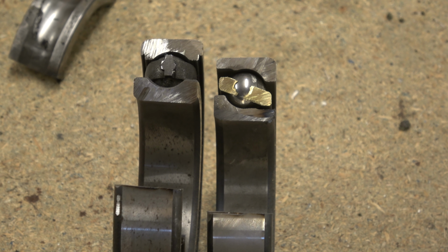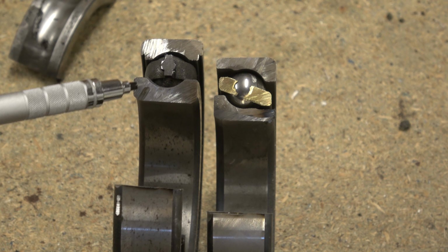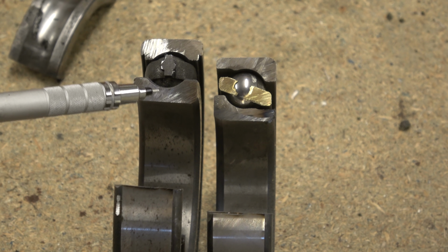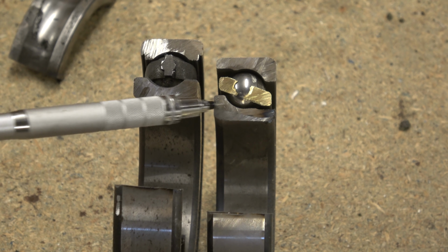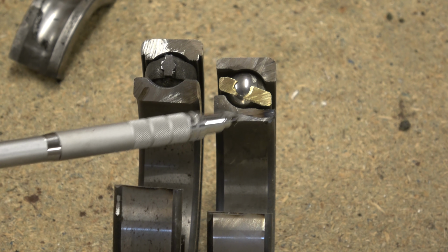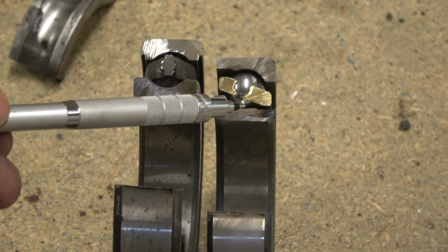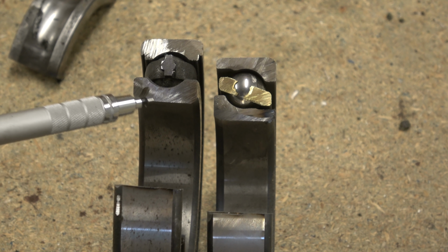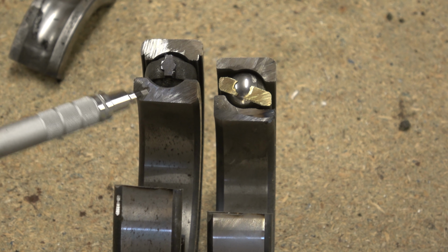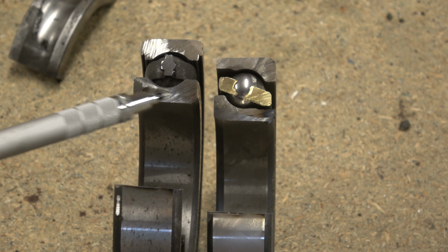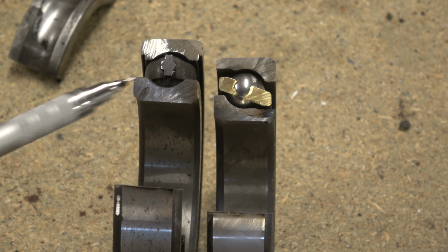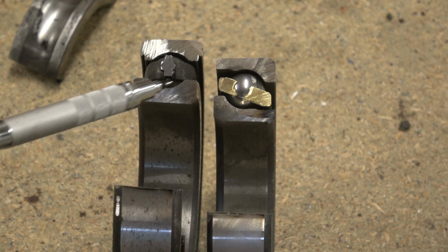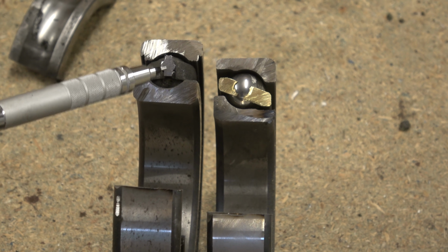So the bearings have been cut up, and what you should be able to see is the difference between a deep groove ball bearing, or cartridge bearing, radial bearing, which is the one on the left, and an angular contact bearing, or some people call these cup and cone. This isn't actually a cup and cone bearing, on the right. First thing to notice is the deep groove ball bearing is symmetrical. It might seem like an optical illusion as though this isn't symmetrical, and that's mainly because I haven't cut it completely straight, but that is symmetrical through that axis.